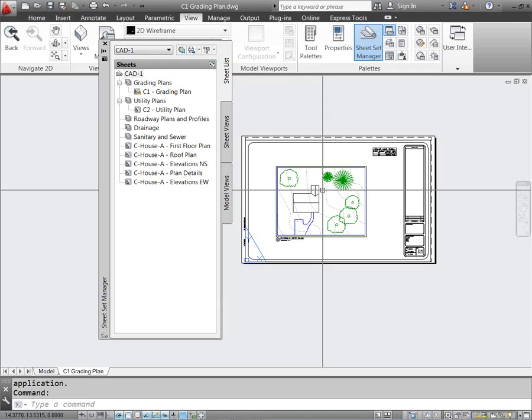Make sure everybody's on board and understands how to use it, because if somebody starts creating individual sheets on their own, not using the Sheet Set Manager, you're going to have one-off situations. You'll have a drawing that doesn't cooperate or coordinate properly with the other sheets. You could also have somebody accidentally ruin the structure, and you'll have to rebuild that drawing from scratch.